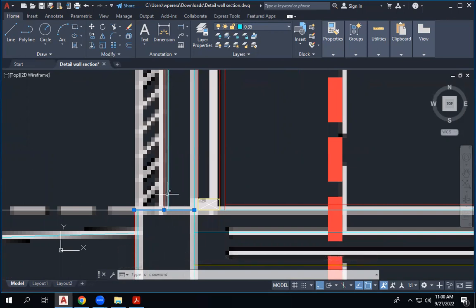If this wall stops before this foundation stops, we have to have that line even though it's the same material. Because in the projection you see now this wall stops here and the foundation goes more forward. So even though it's the same material, you have the line visible. But here we section it at the same level, so we need not have it because it's the same material going all the way down. The concrete grading doesn't matter. We are not considering that. That's the structural engineer's point of view. But in our drawing, we will have it continuously.